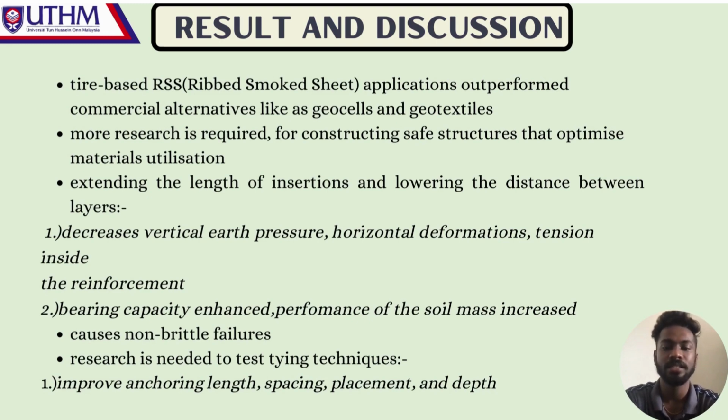Overall, research reveals that extending the length of insertion and lowering the distance between layers decreases vertical earth pressures, horizontal deformation, and tension inside the reinforcement, while also enhancing bearing capacity. It also increases the performance of the soil mass, acting as if it were a completely new component, and it causes non-brittle failures. More research is needed to test these tying techniques and to improve anchoring length, spacing, placement, and depth.